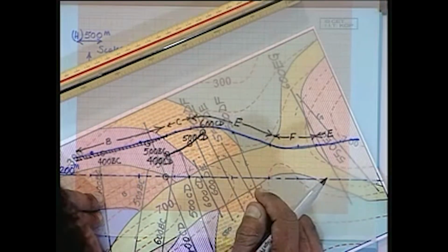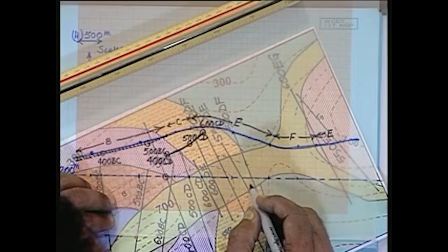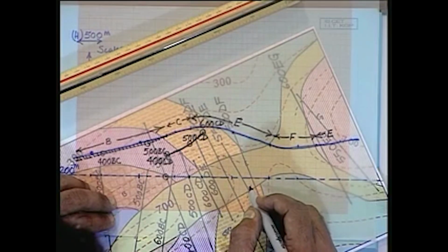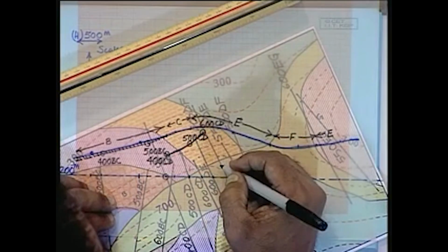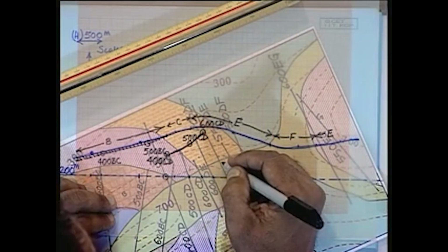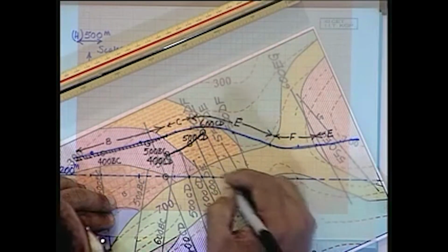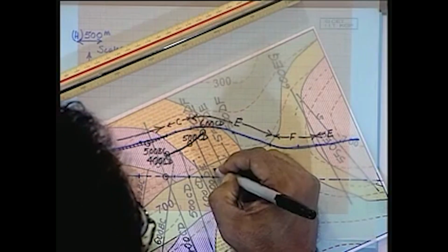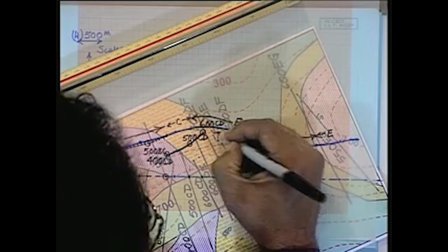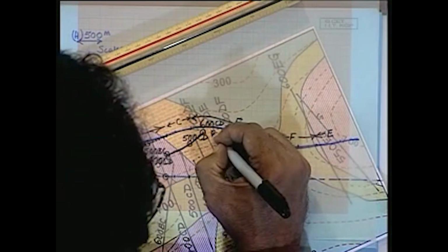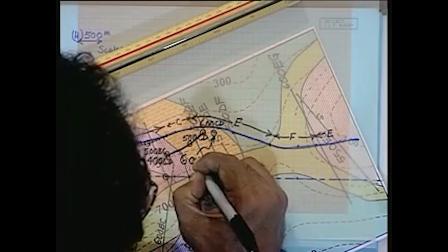So now what should we do? We are going to start marking up in a similar manner the profile of the interface between D and E. So this is the strike line intersection for elevation 600 and the section line. So project that one up to 600 meter elevation. So we come to this point, and this is going to be 600 DE.